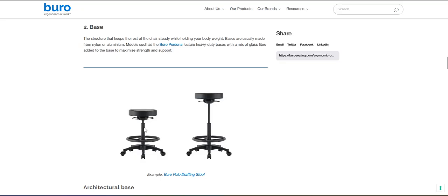Okay, and we're going to have inside the seal, which is going to be made usually of rubber to have the gas cylinder operated. This part can usually be made by casting, if it's going to be aluminum, or plastic injection molding if it's going to be made from plastic. Sometimes they have a plastic with internal reinforcement, which is the same process as plastic injection molding, but they're going to have a preset ring inside the mold.